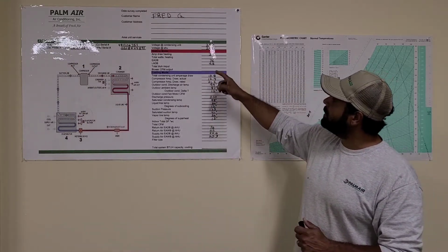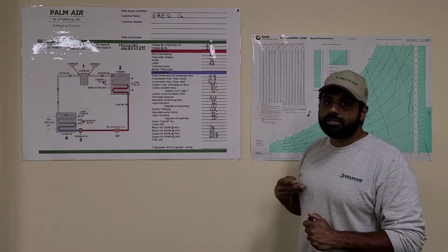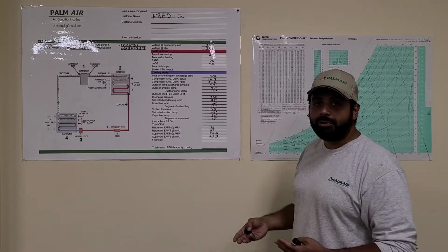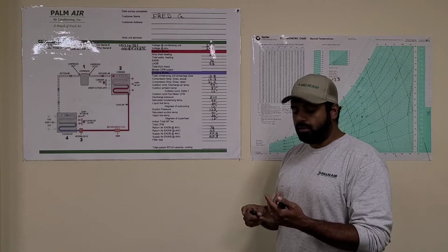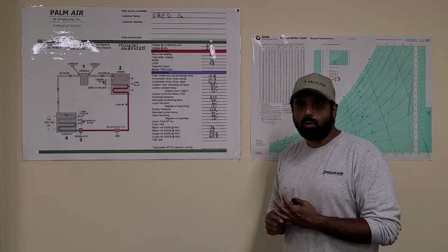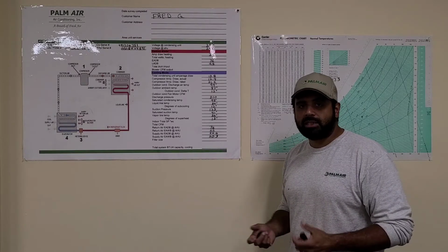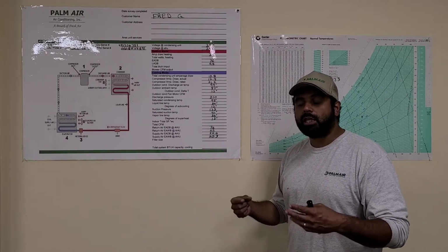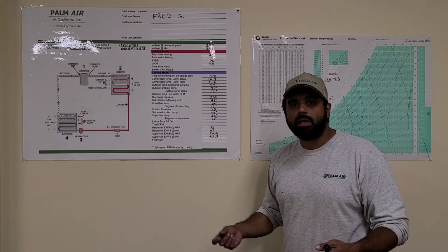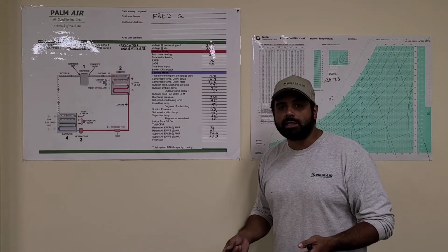One of the first things our guys do when they're starting a unit up is check the heat, one, to make sure it's wired properly and working well, and two, because it's an easy way to determine CFM. So the first equation we're going to get to is called the heat rise method for calculating CFM.